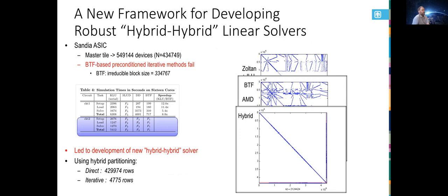I will say, a lot of the time the design flow that people typically use for circuits this big doesn't include Spice, or it doesn't include it much, right? You're mostly just simulating standard cells or something like that, and then calibrating timing simulators. We had a few use cases where people really wanted to run Xyce or Spice on a full design, and that had to do with radiation effects, and the approximations that a lot of digital tools made didn't really make it very easy to look at certain radiation effects. So that was the rationale for why we were doing that. Okay. I wouldn't say that we don't run 500,000 device circuits every day, but that is one of the targets of our work.